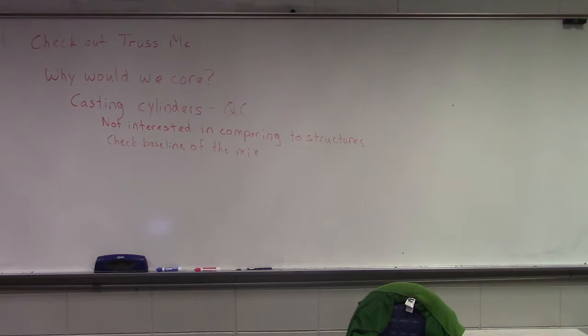So if you did that out in the field, would it be like, okay, these 6 trucks all got the same batch, or do you have to do it per load? That's going to depend on your project. I was overhearing a gentleman talking about shotcrete placement yesterday where they test every truck. And that sounds absolutely awful. That's just going to completely bog down your day. What I would recommend is I would probably check the first 3 trucks of the day.